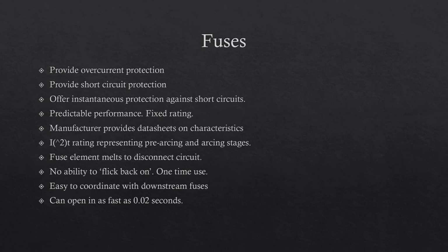So, mentioned earlier was fuses. There's different types of electrical fault. Two key ones to focus on: overcurrent, short circuit. Overcurrent can not necessarily be an issue with the load, but it's just when the load begins to take an excessive amount of current.